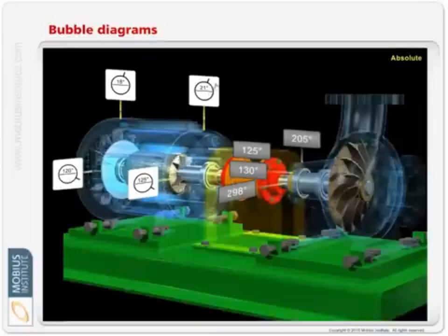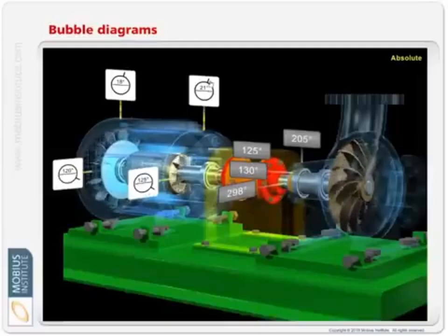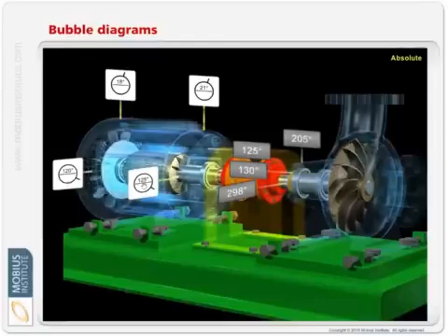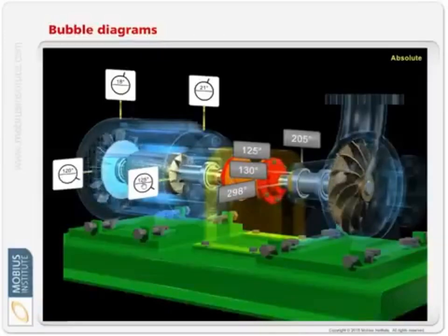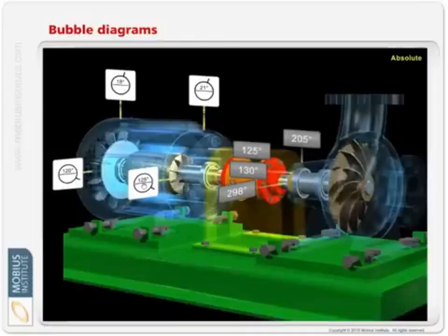It's not 45, but if I compare this one to that one, you can see that there's about 90 degrees between these two. And we only see that with unbalance. It might seem strange, because it's moving in a circular motion and so on. Why wouldn't that always be the same? Well, with misalignment and just about every other fault condition, we see different motions of the machine.